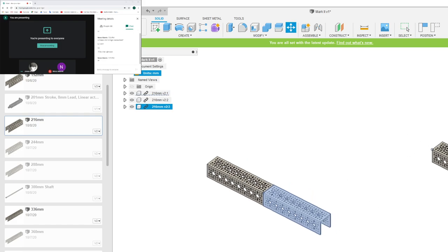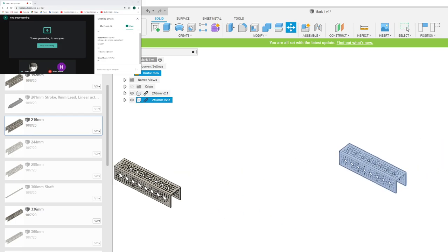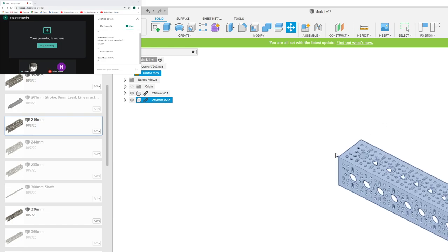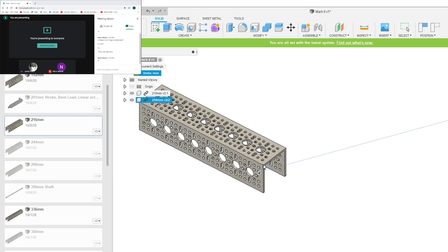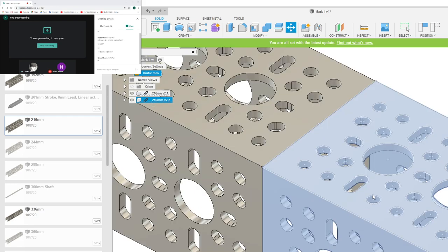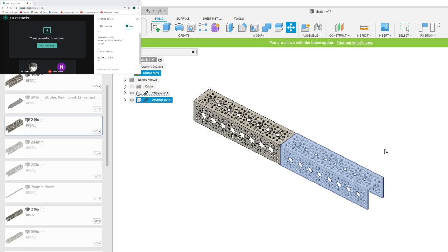There's also origin points and target points. The way this works is if I select something, I hit move, and I bring up point to point, it'll automatically load the origin point. So I come here and I select the origin point, and then I select the target point. The origin point makes whatever it is move. What I mean by that is the origin point is basically what you're moving.